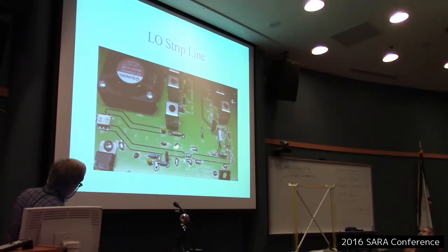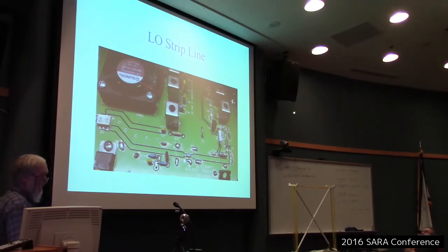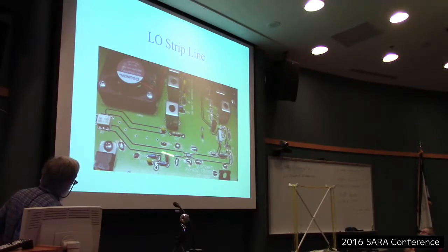And that'll turn an area like this into something that actually has signal currents flowing along at 400 megahertz. Again, at 20 megahertz, 30 megahertz, that type of thing would be perfectly acceptable construction. But we're talking 400 megahertz, 1420 megahertz, and maybe higher in a lot of the radio astronomy stuff. And a little violation like that could leave impedance bumps in the cable and radiation sensitivity. You could run into things where you put a finger on the circuit board here and the circuit quits working or becomes erratic.